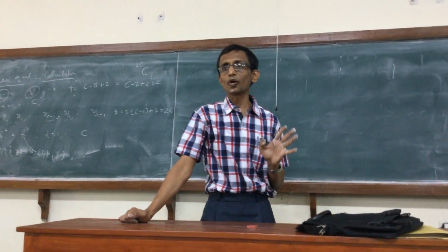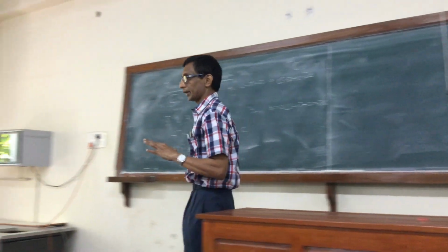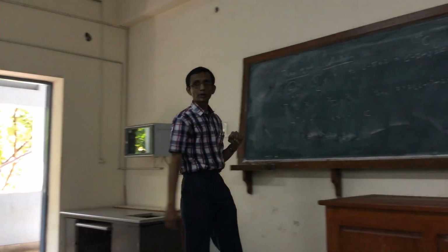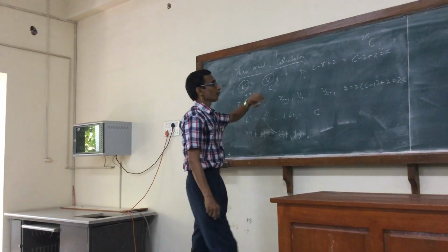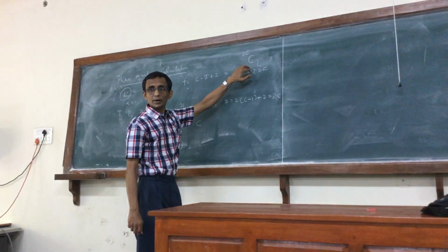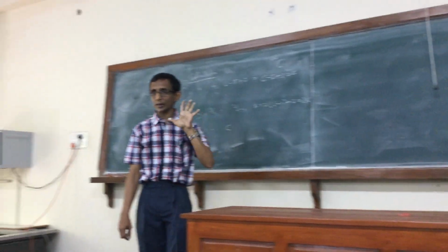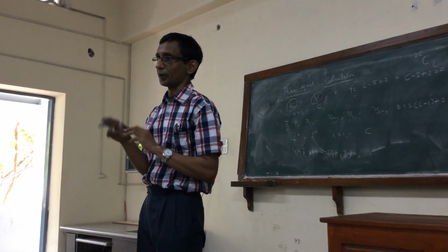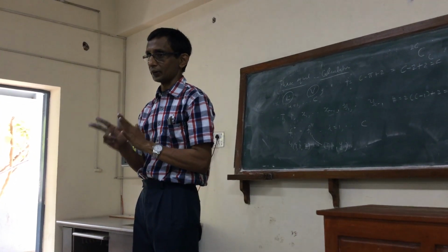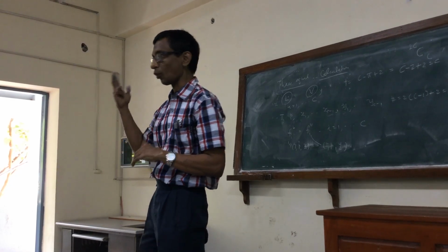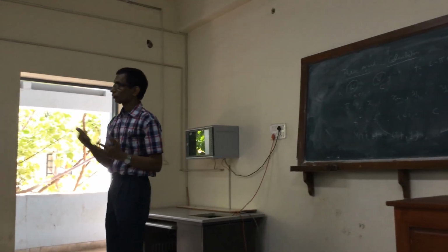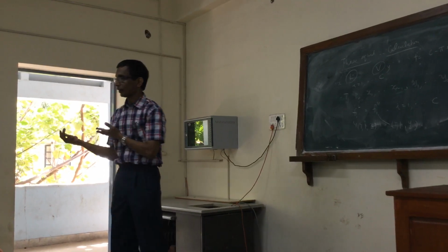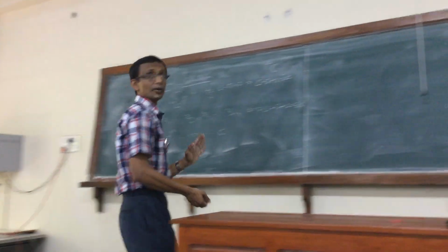In practical calculation, there are four important types of calculations which I will list. Whatever you do, you don't have any right to choose more than C variables. I can choose any possible combination from the 2C variables, but I can choose only C variables. That's what the degree of freedom allows. If I choose more, then I am over specifying. If I choose less, then I am not specifying enough, so I won't have enough information to get the other variables. You have to always keep that in mind.